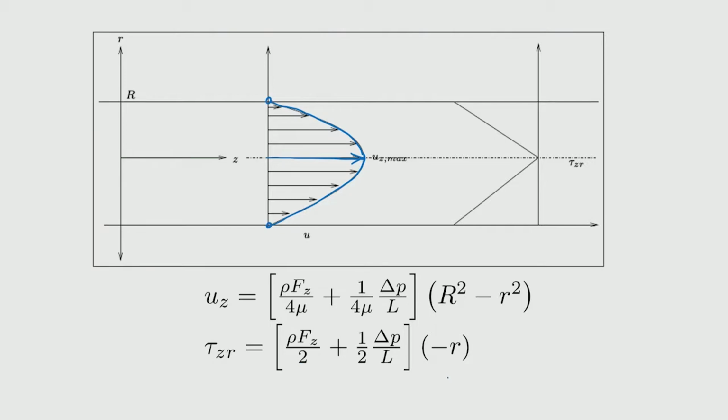Now, you can already see that from Newton's law, the slope of the velocity profile should indicate what kind of shear stress is present at that particular location. So, you can see that the slope is 0 here, which means that the shear stress is 0, and then the slope is actually here. It appears as if the slope is changing sign when you go from here to here, but please remember that this is a cylindrical case. So, this is r and this is also r. Okay. Because of that the slope actually has the same sign on both sides, and that is negative.